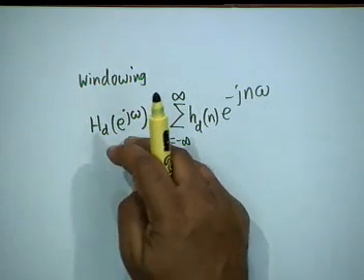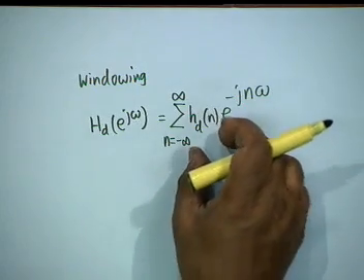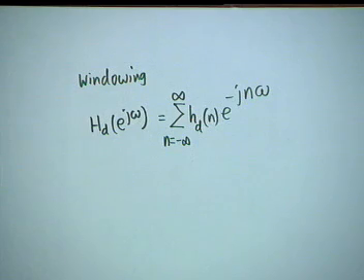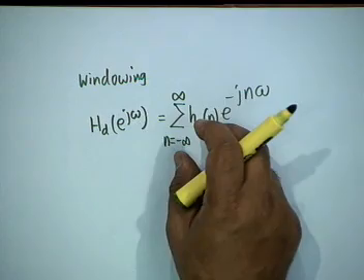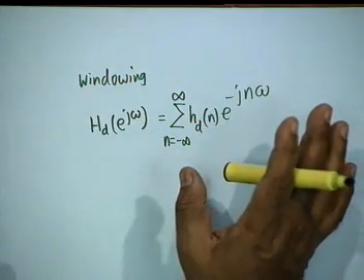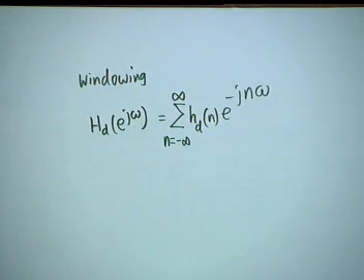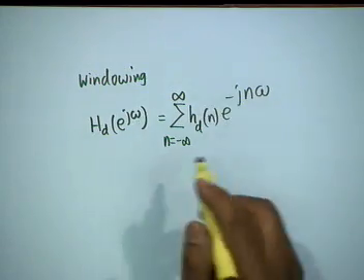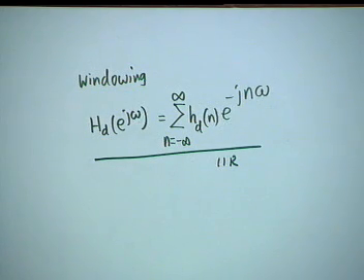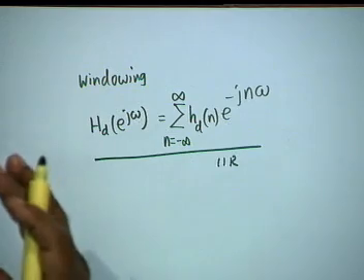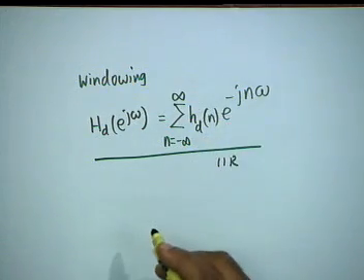Agreed? So given a desired transfer function, and this is FIR, you will have not FIR. h_d(n) shall be of infinite length in general. Agreed? But what you do is you first expand in Fourier series, and then you argue that this is IIR because h_d(n) is of infinite length, and arbitrarily, this is where the uncertainty comes, arbitrarily you truncate it.